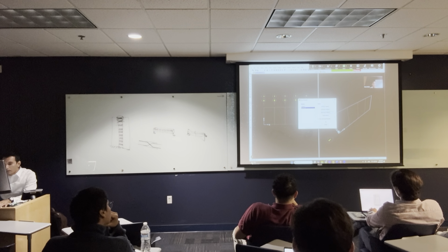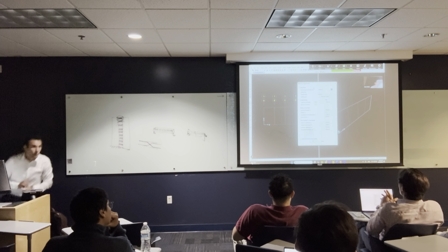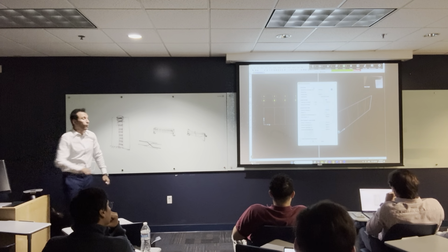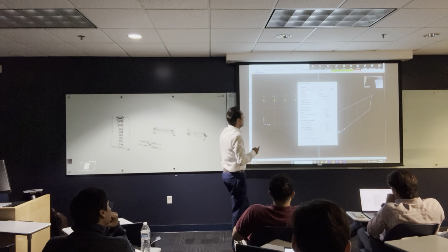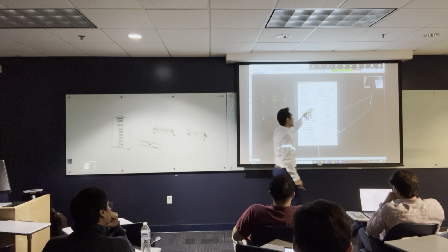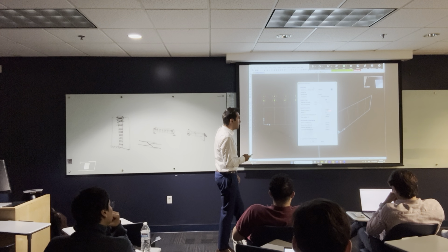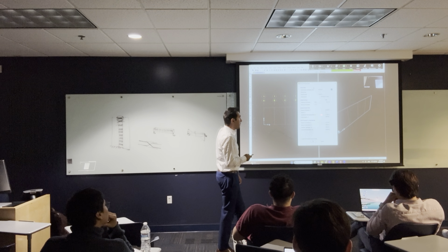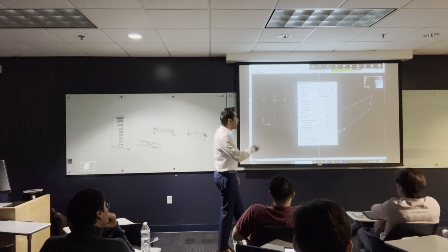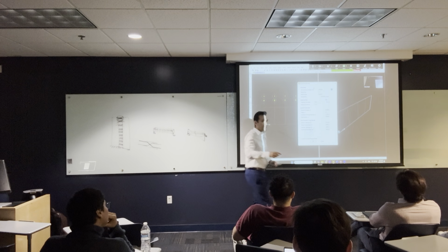Same thing with the steel. I'll modify and show. If you are using steel cross sections for this truss, you have to define the steel material parameters. So same thing, you are going to have the material name, and the weight per unit volume. The steel is always 7.8 ton per meter cube, and the modulus of elasticity, and the Poisson ratio, which is 0.3, the coefficient of thermal expansion, and the yield stress and tensile stresses, because the steel has multiple pieces of information.